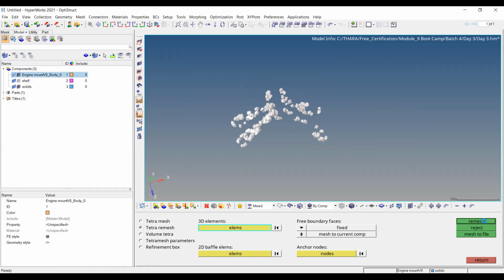What will the remeshing do? It will try to adjust the element within that boundary only. Within the 2 rows of this boundary only, it will try to create the new element. But it will not make the element come out of the CAD. It will not do that. For doing a remeshing, it will take a few extra minutes compared to creating new elements.